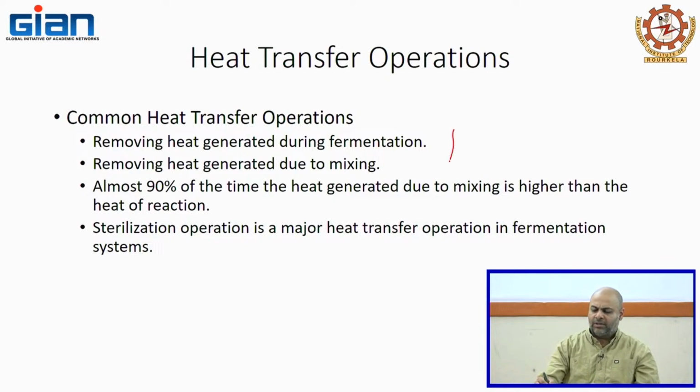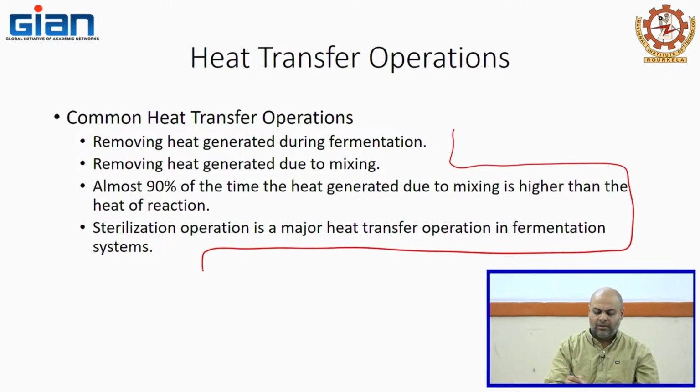Coming back to this, what sort of mode of heat transfer is this? We are looking at convection, but mostly we are looking at heat exchangers. If it is internal coils, it is like a heat exchanger, and the LMTD has to be included.